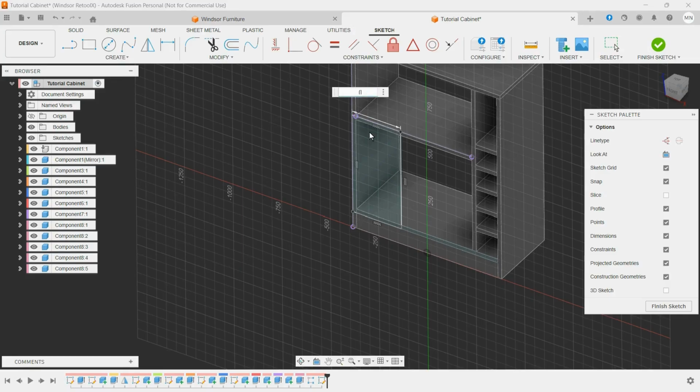So we open a bracket and type width, which is the width of our whole cabinet. To that, we subtract the bottle width and one of the MDF 75 that we have.